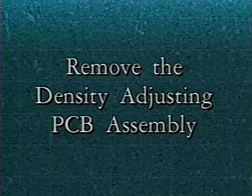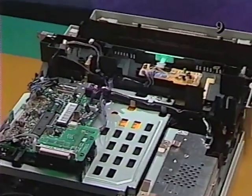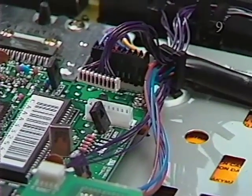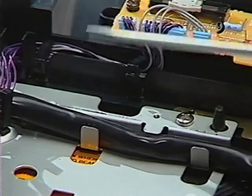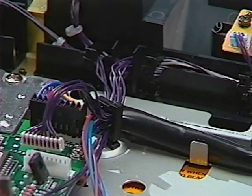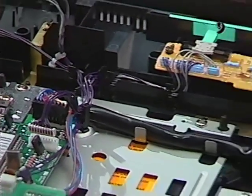Remove the density adjusting PCB assembly. First, disconnect connector J213 from the DC controller PCB. Open the three black cable clamps located on the side of the inner cover. Now open the black cable clamp located behind connector J212 on the DC controller PCB.